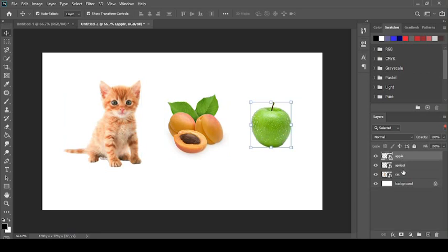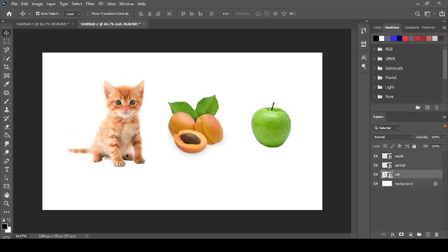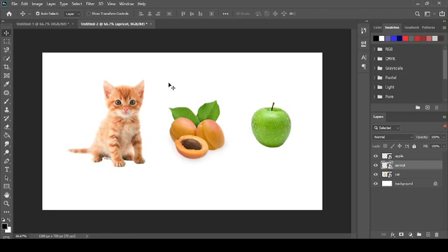When you select the layers, you can see how to select the objects. Before moving an object, you should select Show Transform Controls on the option bar. When it is not selected, you cannot see the transform margins of the object. It is difficult to identify which object is going to move. So it will be easier if you select Show Transform Controls on the option bar.